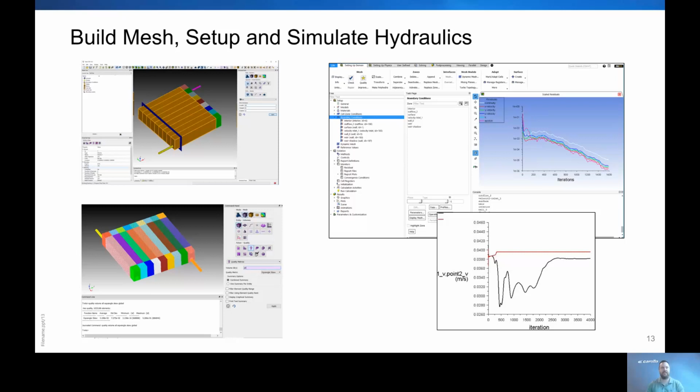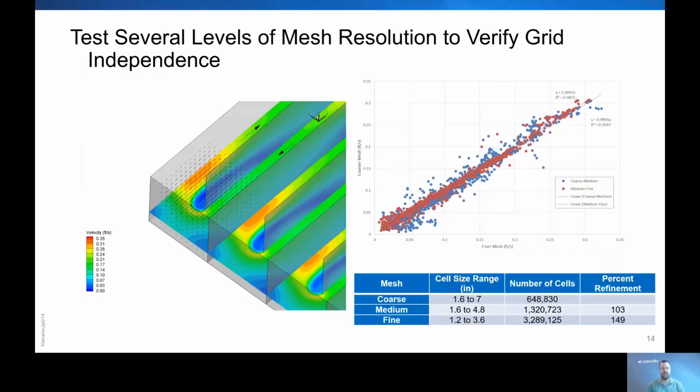We need to make sure that the mesh resolution is good, that we have enough cells to solve the problem we're looking at. And so mesh sensitivity test is typically performed for problems that have risk, such as baffle factors, which directly apply to public health. So here we've extracted a number of data points from the converged solution at a bend where there's some instability in the flow, a point where we think the model might have uncertainty.